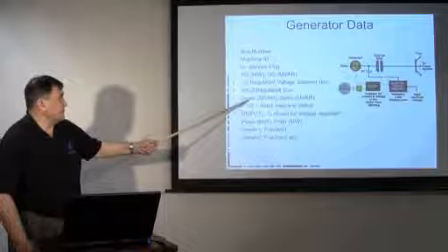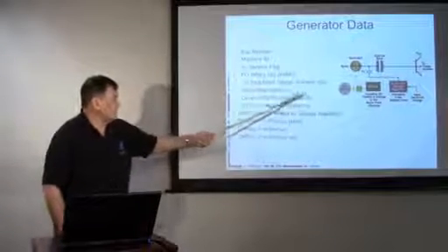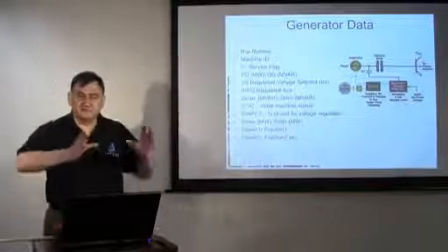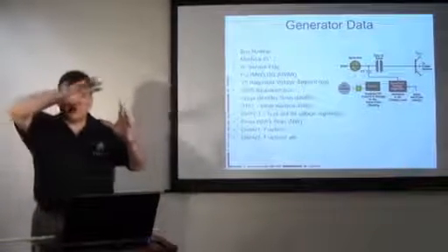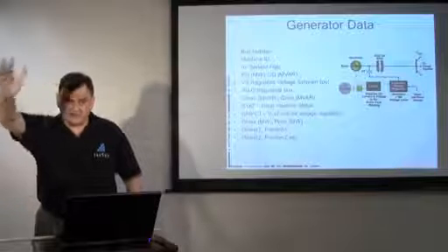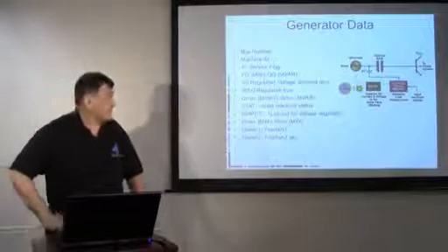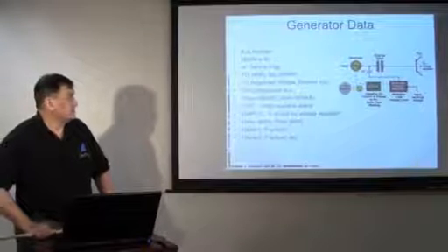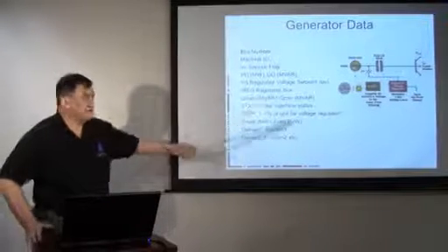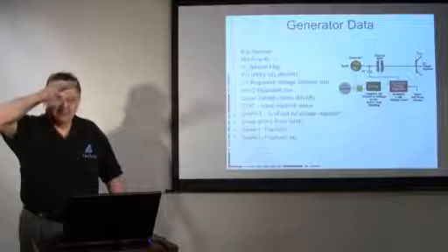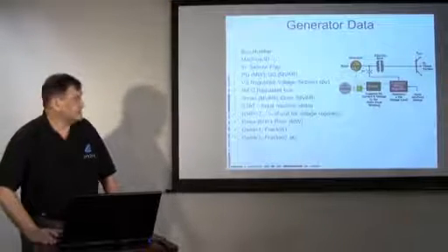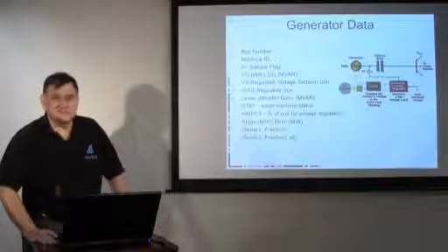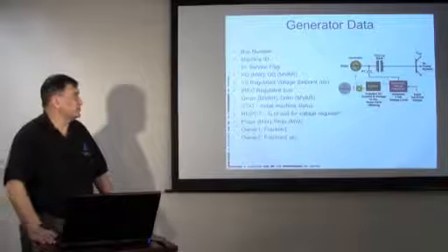We have a maximum megavar out and a minimum megavar of what it can absorb. Now remember back from the voltage class, we talked about a generator really has a capability curve. It's like a D shape representing the different thermal ratings of the field, the stator, and the windings. But for planning, they don't represent that entire curve. They literally just use a single max and a single minimum value. So again, that is a gross simplification. As we get into things like restoration studies, we really need to represent that entire capability curve.